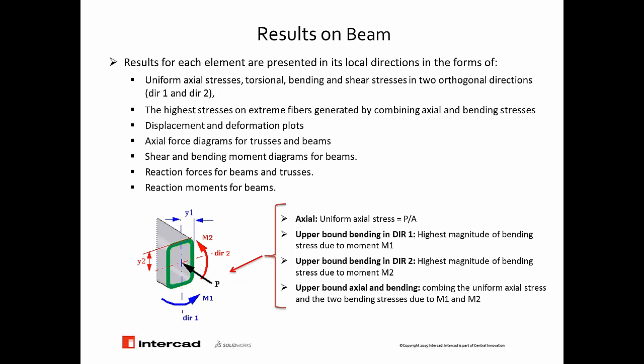We can also get the highest stress on extreme fibers by combining axial and bending stresses, displacement and deformation plots, axial force diagrams for truss and beam, shear and bending moment diagrams, reaction forces and reaction moments for a problem like a beam which is subjected to axial forces and moments in different directions. So all of what we can see in the list can be reviewed and you can make your decision on their magnitude, whether it fails or passes or meets the standard of your design.